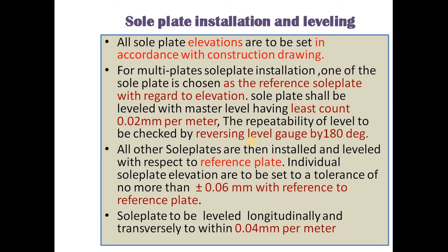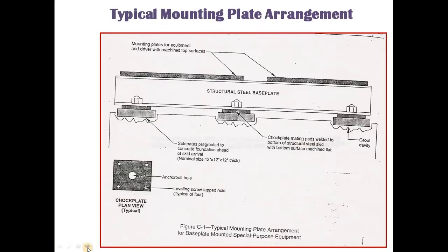Before doing any alignment, we have to do the sole plate leveling. What is sole plate? If you see the drawing, there are so many sole plates we are using on the foundation block, concrete block, and this sole plate is to be grouted with the foundation block. The sole plate is located longitudinally as well as crosswise, transversely. This sole plate needs to be leveled.